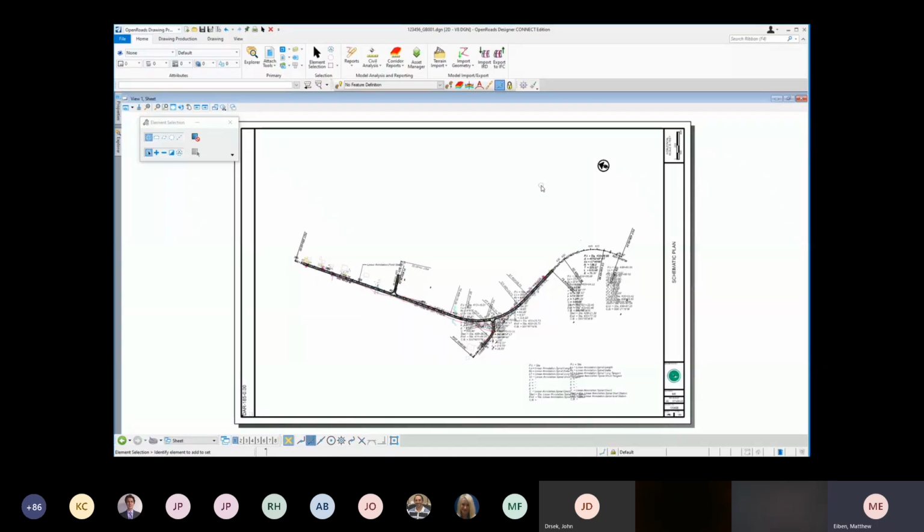Okay, now we're going to take a look at recreating the schematic plan that we just created with that traditional workflow, and we're going to reproduce that using a name boundary workflow. Before we move on, it's worth pointing out that if I snap to the lower left corner of this sheet boundary or sheet cut line, you'll notice that the coordinates kind of match the project coordinates here. With the name boundary workflow, our sheet border, that corner there, is going to be placed at 0-0.